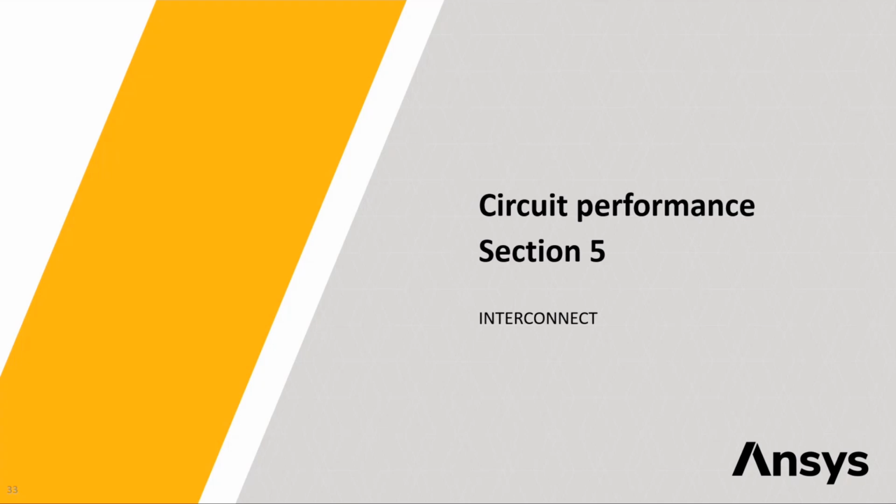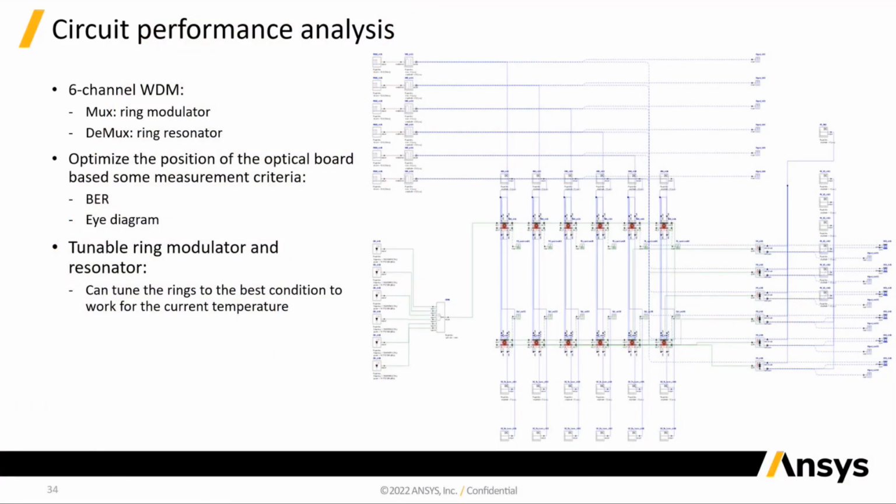This part is in the numerical solver, which does the circuit performance analysis. Just now in the thermal analysis, we had a circuit board. Now we convert it into the circuit diagram, which is the schematic inside the interconnect. We also import the data from the charge and FDE, the RF analysis, and the result from the thermal analysis.